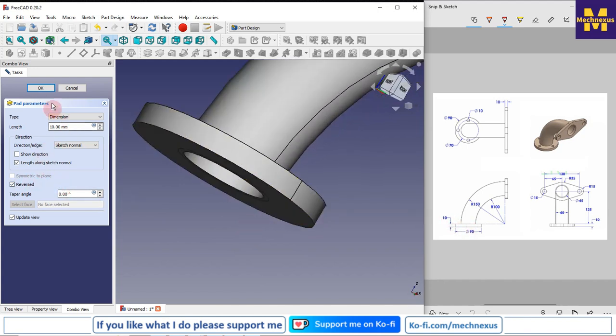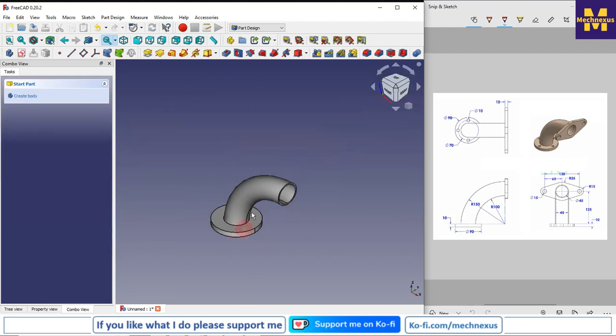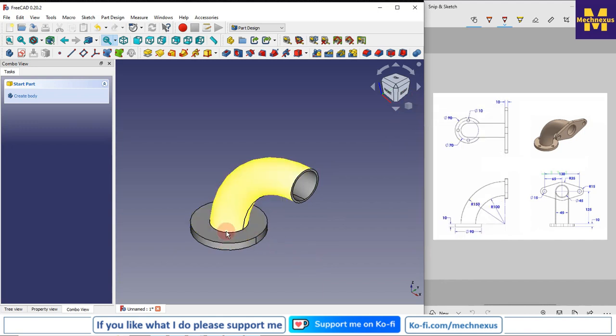Thickness is 10 mm, so 10 mm is there. Now I will switch to the isometric view by pressing the 0. You can see the shortcut here for isometric orthographic. And now there are 3 holes, but we will make 4 holes because in general flanges have 4 holes, or 6 holes, but it should be at an equal angle between the 2 holes.